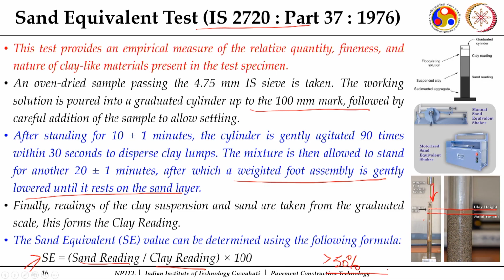previous slide. So this controls the amount of clay which can be present in your fine aggregates, because the clay, and we are ensuring through plasticity index also, but we are going to ensure through sand equivalent value also to control the presence of fine materials.